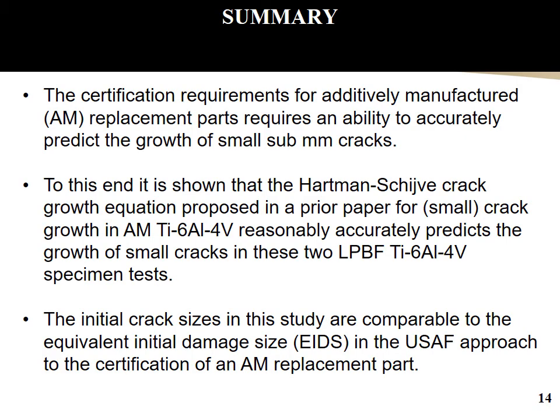Now to summarize. The certification requirements for additively manufactured replacement parts require an ability to accurately predict the growth of small sub-millimeter cracks. To this end, we've shown that the Hartman-Schwalbe crack growth equation that was proposed in a prior paper for the growth of small cracks in additively manufactured Ti-6-4 reasonably accurately predicts the growth of small cracks in these two additively manufactured specimen tests.